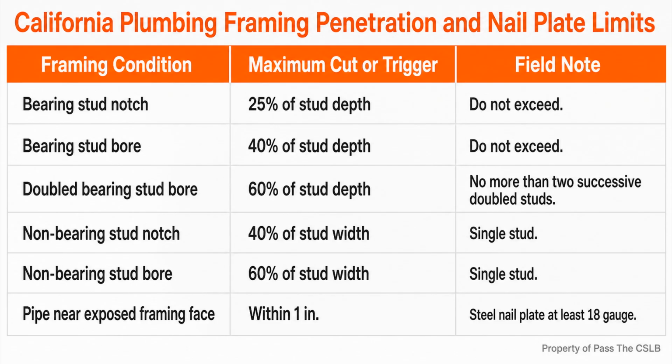Suppose a subcontractor caps a new plastic drainage system and reaches for an air compressor because it is quicker and cleaner. I would stop that test. Schedule pressure does not change the material restriction. The safe field decision is to use the approved water test and keep people clear while the system is filled and inspected. This is also a documentation point.